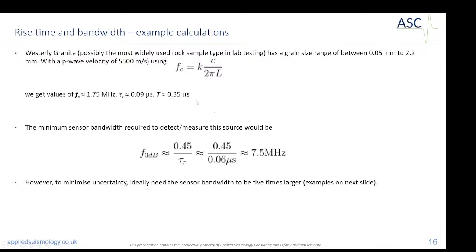we will want to have, in this case, an instrument with a corner frequency covering something in between 1.5 and 2 megahertz. Of course, we need to work with a wide bandwidth. So the minimum bandwidth required has to cover above this corner frequency and below it. So we want the 3 decibel band to be, in this case, what is recommended, around 7.58 megahertz. So, these are the considerations that we need to take into account.